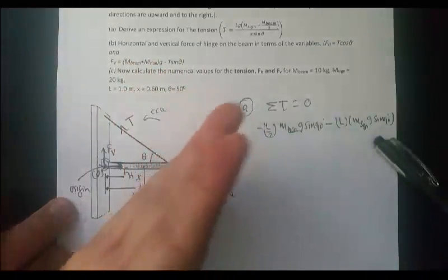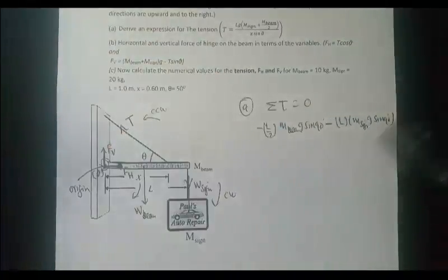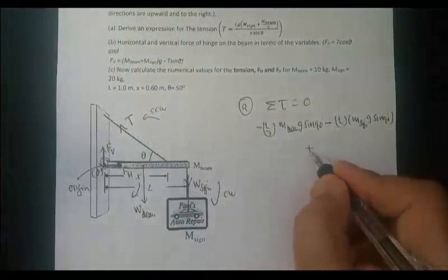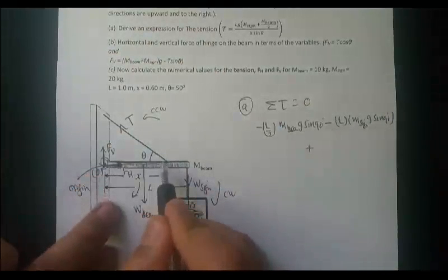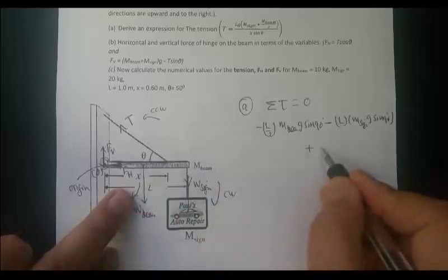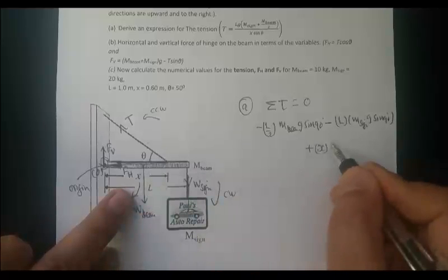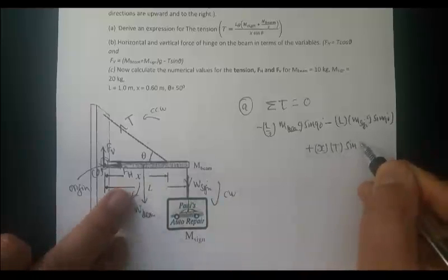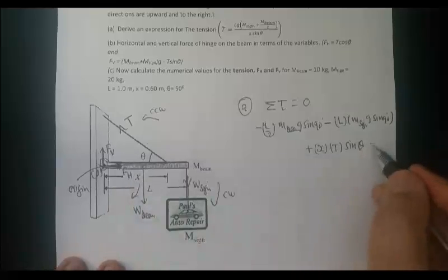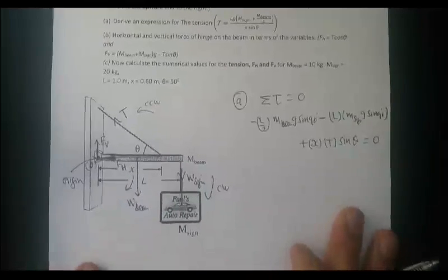If you use this rule, out of the z axis is positive z, plus. But this cable is attached at distance x, not L. So R is x, force is T, and sine of the angle it makes, 30 degree, which is theta. We're going to solve all these in terms of symbols.